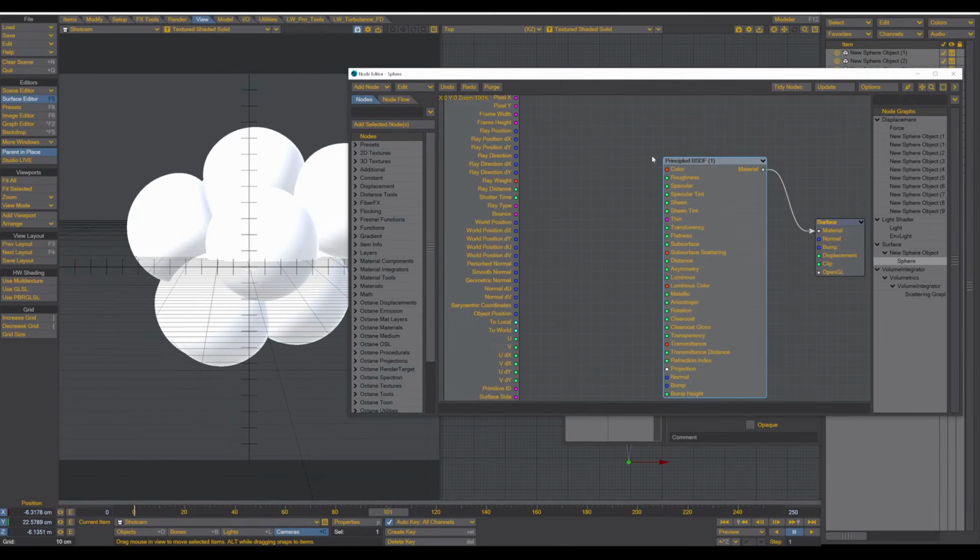We have the Principled BSDF as the shader model. And now what we need is an instance info. The instance info tells us we have 10 individual spheres, so every sphere is an instance, okay? And we can drive with the fixed random color or the index ID which color goes on which sphere.